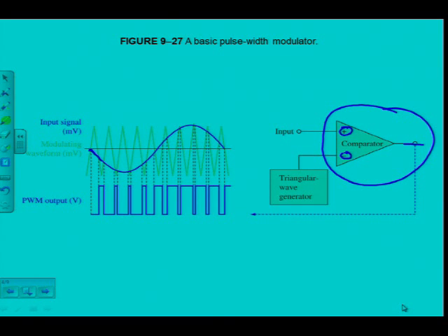Remember we said here, as the signal goes negative, there's my modulating waveform, that square wave waveform, and there I can see it switches to the negative state. Every time now as it becomes more negative, I can see it switches for longer periods, and then as it becomes more positive, I can see again that the pulse width on the positive side becomes bigger, as it corresponds there with the sawtooth waveform that is applied there as the modulated waveform.